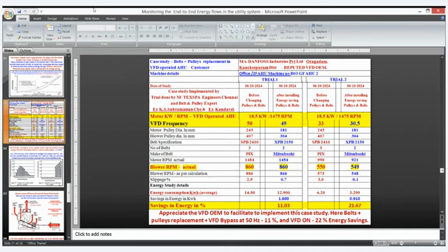This is a very low cost, instantly implementable solution, and with no EC fan there, which costs more, and the total system change is happening. But on the existing system, on the same motor and the same blower, only the change of VFD settings and the change of the power transmission components, especially from V-belts to cogged belts, which carry more power carrying capacity. And the resized new pulleys.